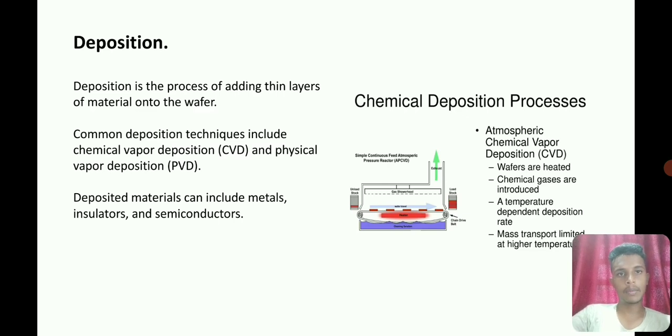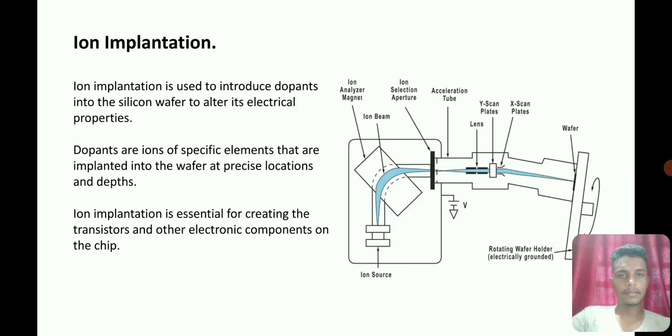deposition is the process of adding thin layers of materials onto the wafer. Common deposition techniques include chemical vapor deposition (CVD) and physical vapor deposition. It's also called PVD. Deposited materials can include metals, insulators, and semiconductors.